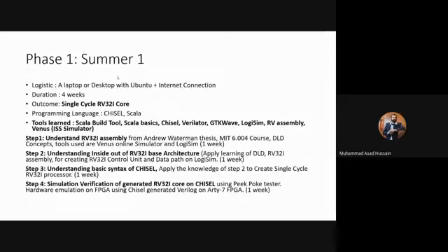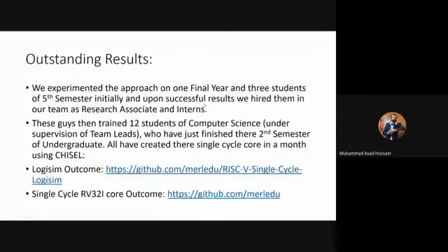You will learn the Chisel basics, and after that you will design the data path that you have created in Logisim, that is RV32I, in Chisel. Verification of that is done using the PeekPokeTester, and for hardware emulation you can do it on an FPGA using the Chisel-generated Verilog. One of the most important features of Chisel is that once you code in Chisel, it automatically converts your code into Verilog. That Verilog code can be ported into an FPGA, and you can run your core with certain programs. We will discuss later in these slides how we have done it.